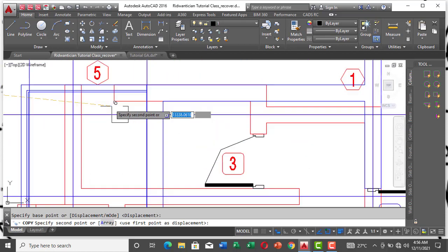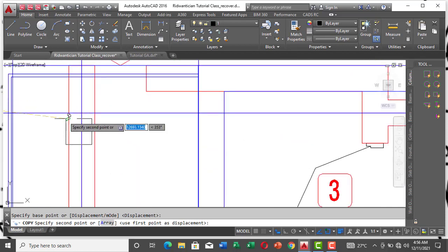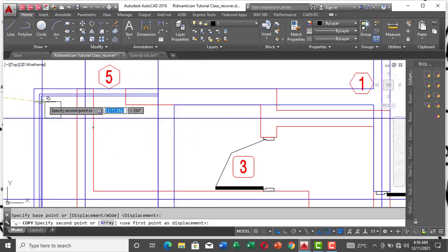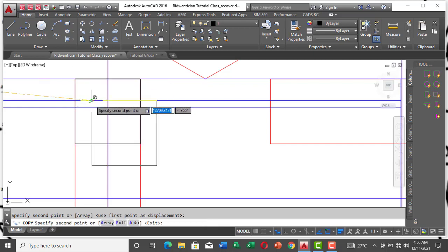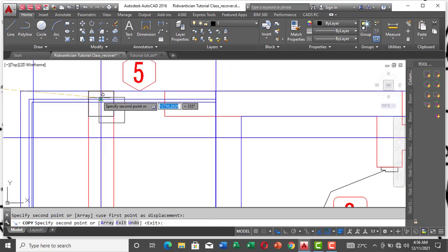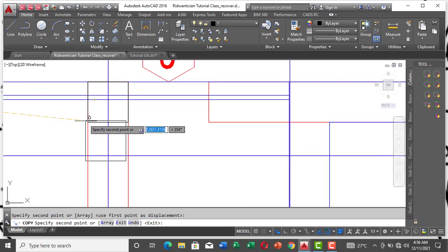Now look at this red line you are seeing, that's the end of the ground floor. You can see at this other place you don't have any red line. So that means this particular point is the four corner of the ground floor, the edge of the ground floor. So you need a column here. However, this column will only work in the ground floor. It should not come up to the first floor,